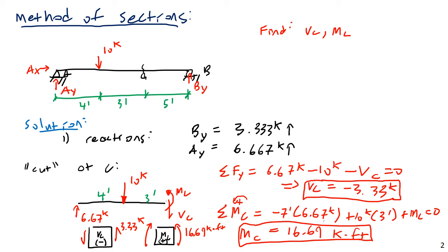Okay. So that's nice and all. This problem is nice to illustrate the idea of internal forces. And in fact, there's one other thing I could show here. I could show that there is an NC here, but that's clearly equal to 0 because there are no horizontal forces. So these are the 3 internal forces that can exist in members. Now NC in this particular one is equal to 0, but later when we get onto frames, we'll see that it is often not equal to 0.